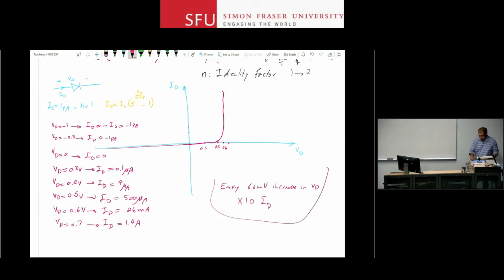So this exponential growth is what is giving us that knee-like behavior, that shifted ideal diode-like behavior. I went through some examples here to calculate the values. You have some examples on your slides for 3 different diodes, with different I's and IS's and N values. Just do a calculation for the current through those diodes and get a feeling of how these numbers look.